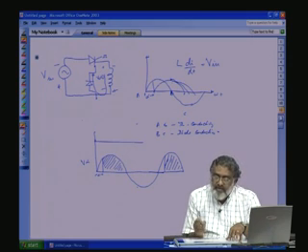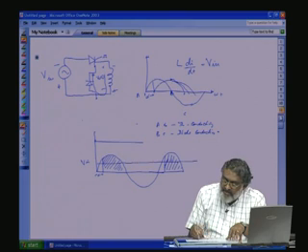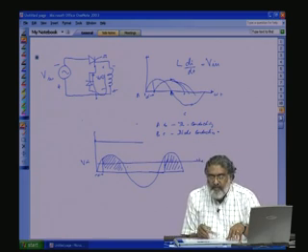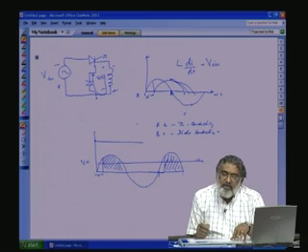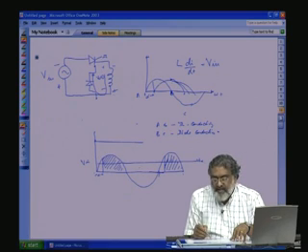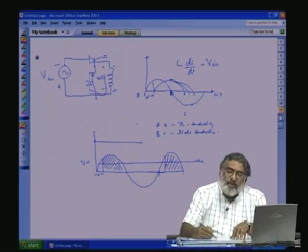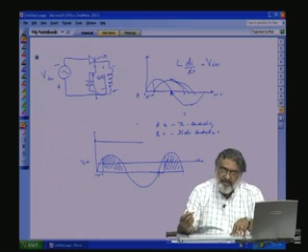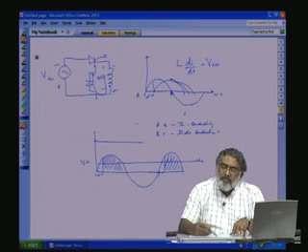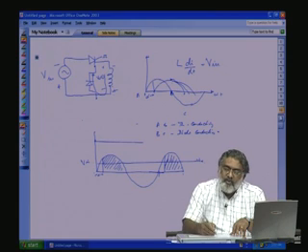At the same time, if this is the V0, that is the V0 alpha VDC, there is ripple associated with the output voltage. So this ripple voltage, what is the frequency of this ripple voltage? It repeats every cycle. So this frequency component will have the fundamental, then third, fifth, all harmonics will be there. For higher harmonics, the impedance L omega will become more and the current drawn by the inductance is less. So if you want to have a pure DC, okay, we have the load.